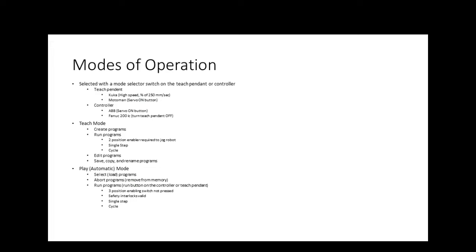So normally when we're in manual mode or teach mode, the safeguards are not in play. That means you can open up the work cell, go in there, place objects in it, and get in the work cell with the robot, right? You understand that while you're programming it. A lot of times when we're writing programs, we have to be in with the robot, because we're trying to verify distances, and see if it grips everything correctly and all that kind of stuff. So this is in teach mode. When you jog the robot, speed is limited to 250 millimeters per second. Why? Because that's been proven to be slow enough that you can get your hand off that e-stop button if the robot is about to hit something, or if it touches you and you're not paying attention. And people do that all the time.